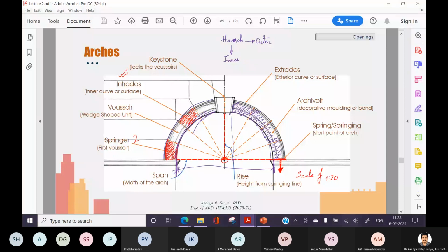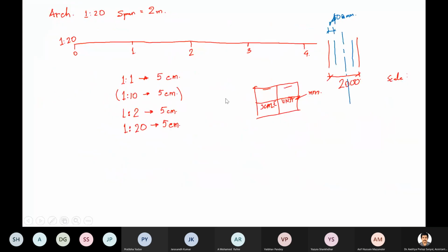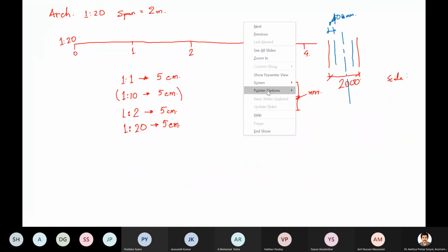Many of you hadn't done the through stones. I told you the concept of the through stones. The sections are not exactly matching where the section line is. Don't make those errors. I probably mentioned that there shouldn't be any vertical lines matching in your masonry sheet.